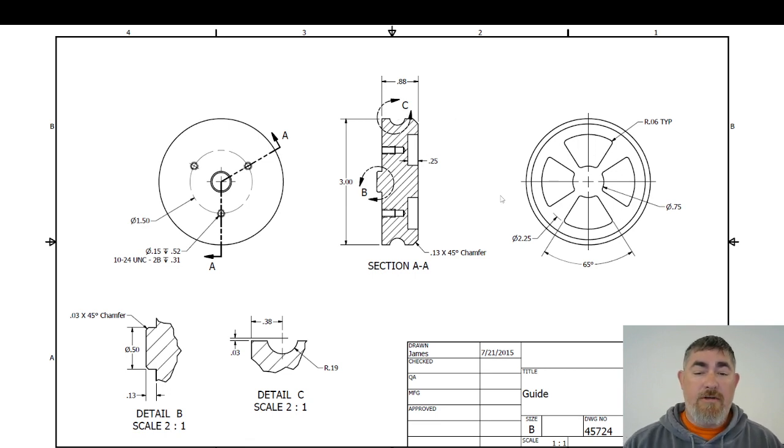And so we can break it into features: the main cylinder, the boss, the cutouts, and the holes, as well as the groove here. If we treat each of those things as its own thing that could be changed separately, it gives us better intent. If we tried to do it all as one, now we're stuck. If we drew half this shape and we decided we want to change this boss, remove it completely, or change what this groove looks like, then we've got to go back and edit the sketches instead of just turning off a sketch and changing that.